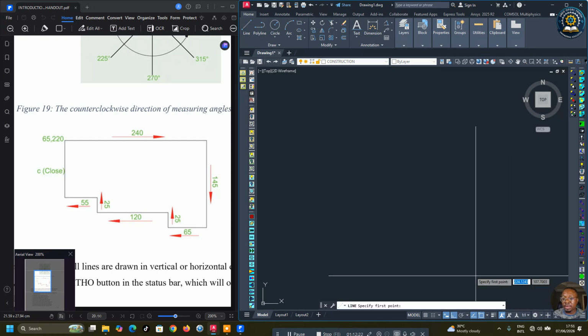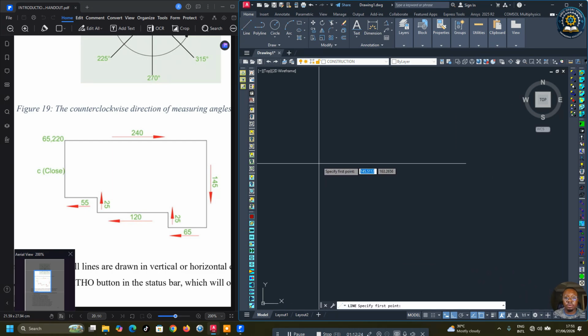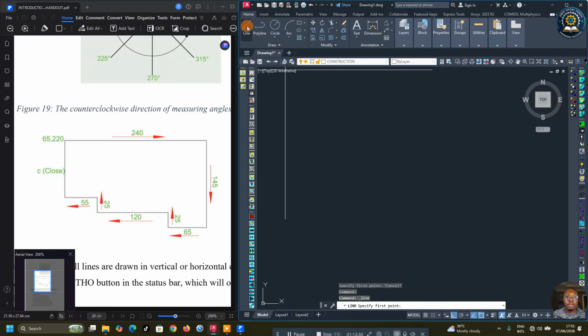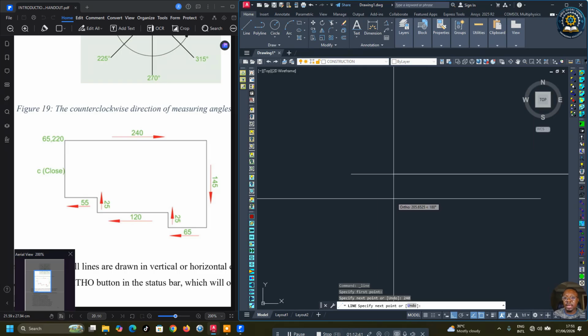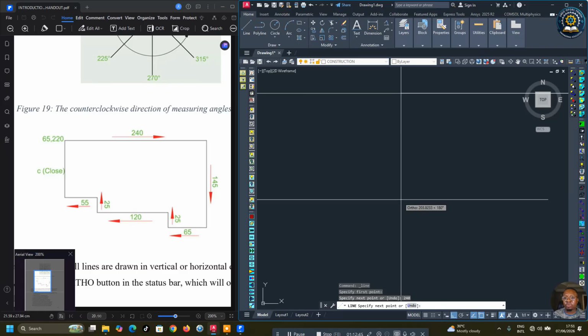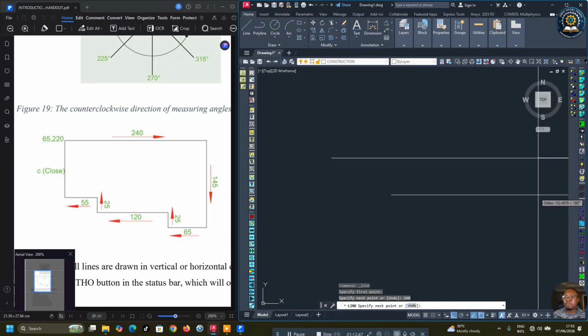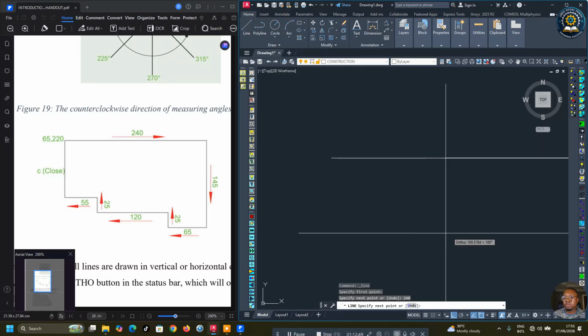and I'm going to turn off the dynamic input for now. So I click on the line tool, click on the first point, move the cursor in this direction, 240, press enter, right? Then I can roll the mouse button up or down, trying to find the end. Now this is happening because I've reduced my workspace.